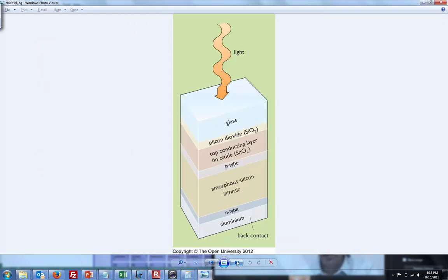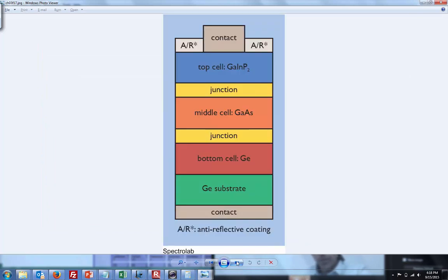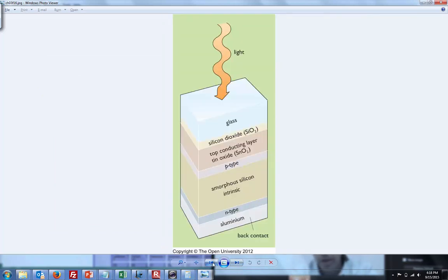So to fix that, there's a little bit of silane gas pumped in, so that's SiH4, and a little bit of boron. You can think of it as like atomic caulking material, something that's just going to go in there and stick to whatever dangling bonds happen to be ready to accept it. Because the hydrogen combines with the dangling bonds and basically seals it.